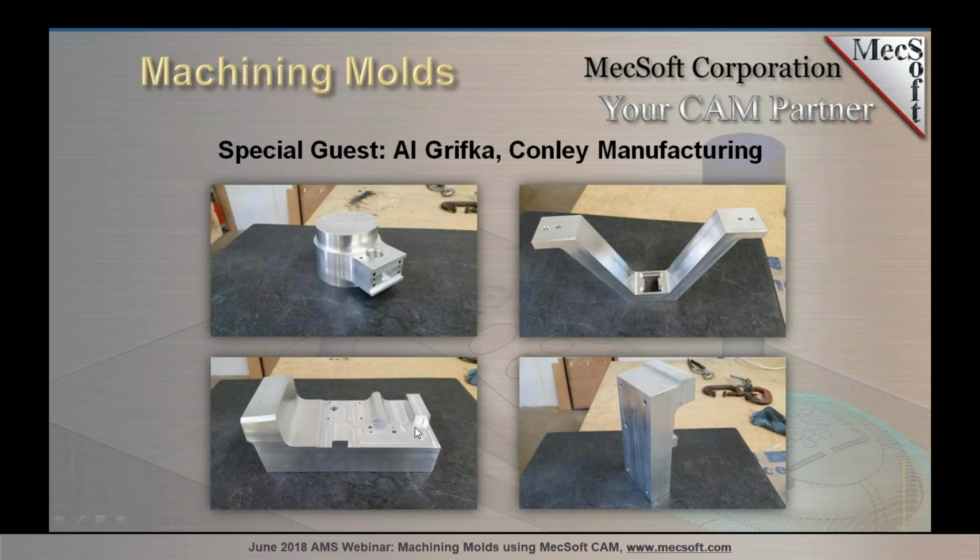This down here is actually a checking fixture, part of a checking fixture block. As a production process, they'll stamp. This is to check sheet metal steel parts, typically between a 1/16 and an 1/8 inch thick. So they would set the part on top of this.